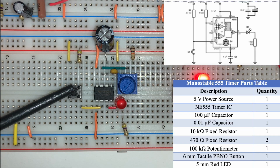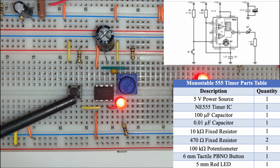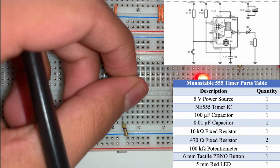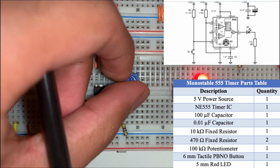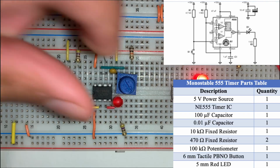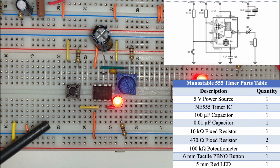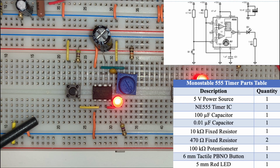In monostable mode, the 555 produces a single output pulse whenever triggered. Pressing the push button pulls the trigger below 1/3 VCC, causing the trigger comparator to set the SR latch. The output goes high, turning on the LED while the discharge transistor turns off, so C1 can charge through the resistor and potentiometer. The output remains high until C1 reaches 2/3 VCC, when the threshold comparator resets the latch.